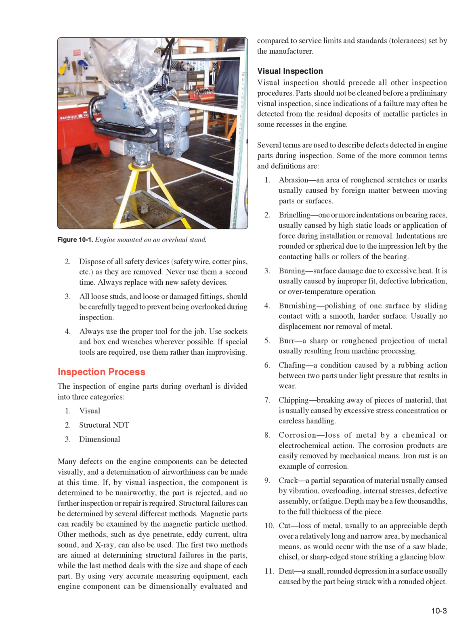It is usually caused by improper fit, defective lubrication, or over-temperature operation. 4. Burnishing, polishing of one surface by sliding contact with a smooth, harder surface. Usually no displacement nor removal of metal. 5. Burr, a sharp or roughened projection of metal usually resulting from machine processing. 6. Chafing, a condition caused by a rubbing action between 2 parts under light pressure that results in wear.